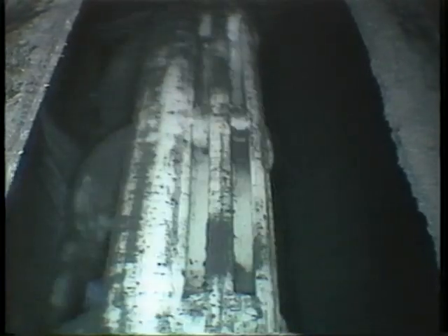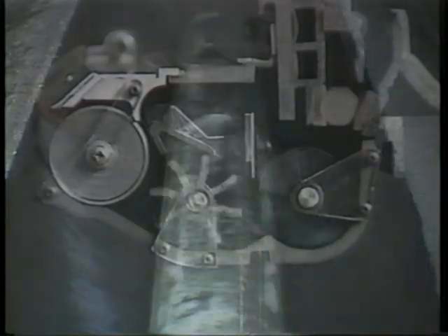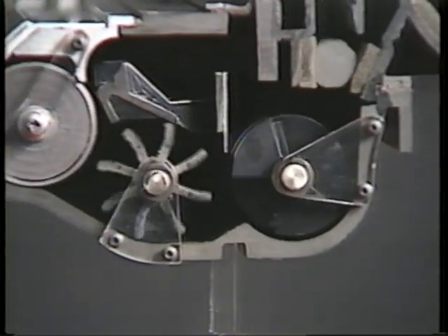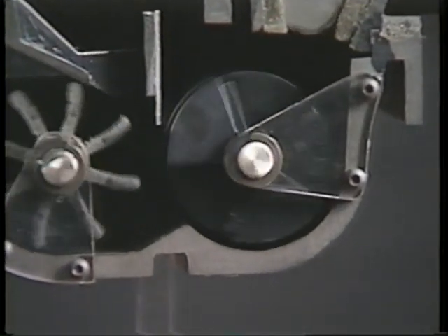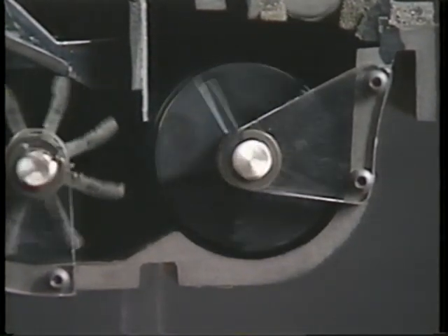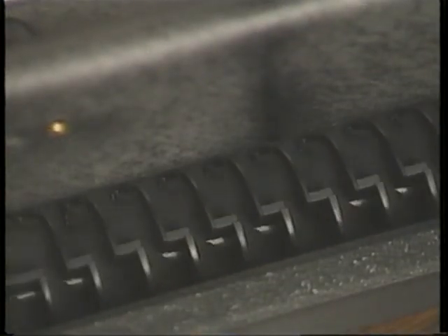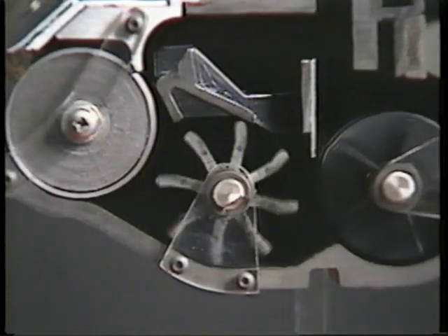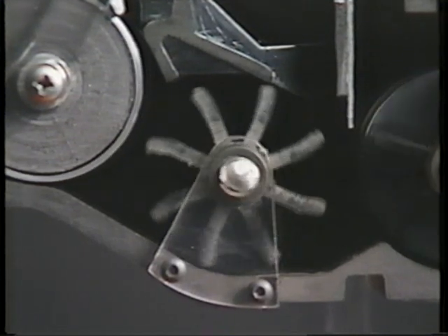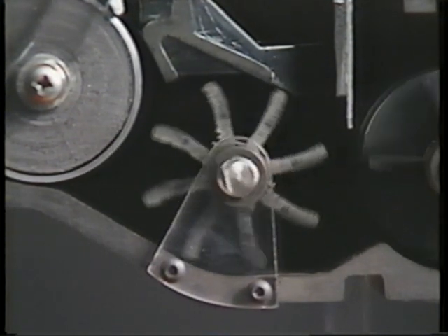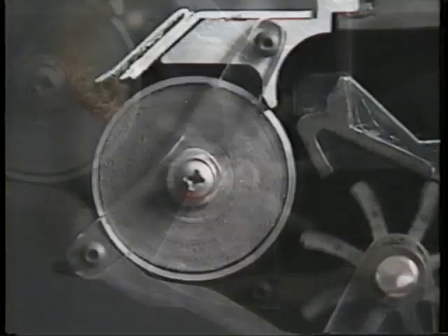Inside the toner supply, there's often an agitator to keep the particles from clumping together. Here's an agitator in the development unit. It mixes newly added toner with the existing supply of carrier to create and distribute the triboelectric charge. This is a paddle roller. It feeds the toner and carrier mixture to the development roller.